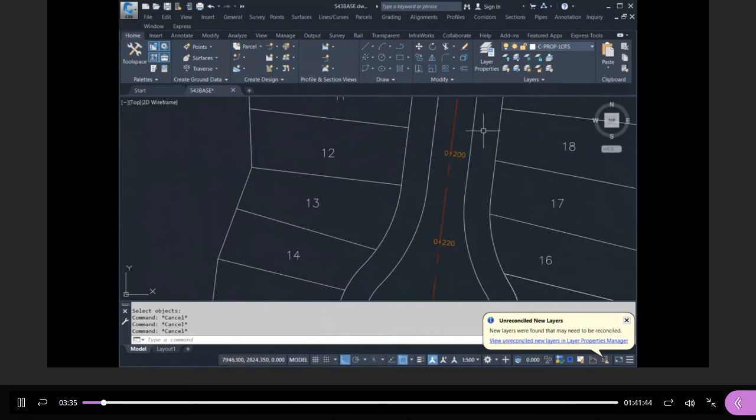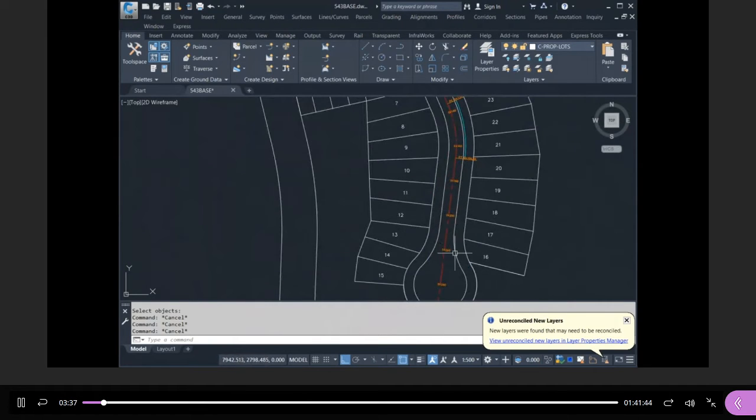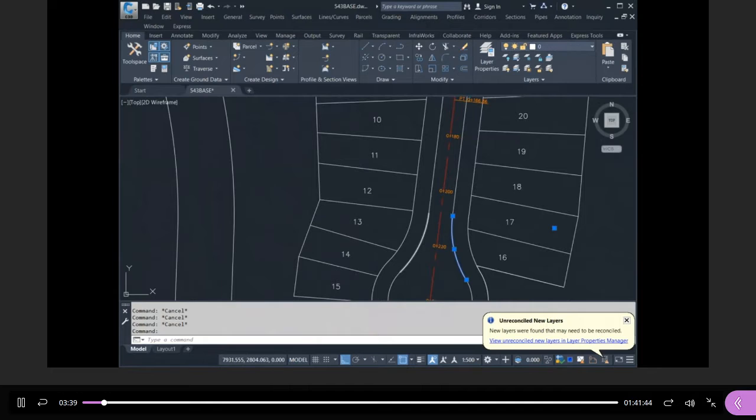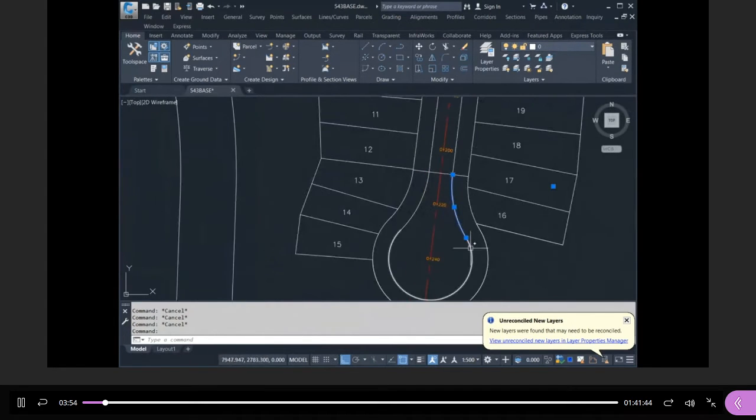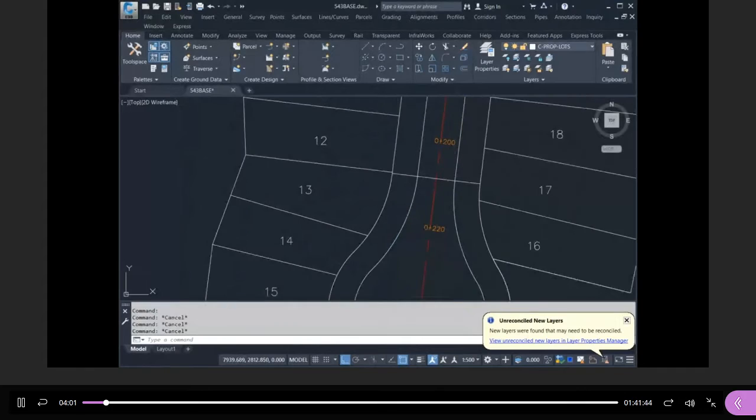Okay, so remember the last time we have a standard 20-meter right-of-way is where the widening starts, right? So right here, these 2 dots, that's the last time. So I'm going to draw that in from here to here. So, along here, all the way to this point here, we have a standard 20-meter right-of-way. Then there's where it changes. So I want to create an alignment along the gutter line that goes all the way around and back again. That's the unusual, non-standard part of this.